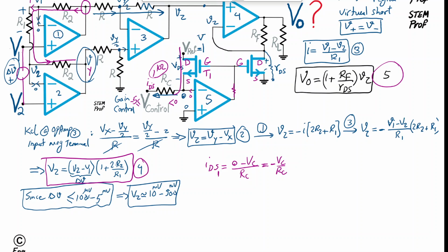Practically, it's usually recommended to have a resistor with a small value, but as I said, there are practical considerations that are not mentioned here because they are not core to defining the operation of the circuit, though they are needed practically. So let's just assume that the output voltage of the op-amp is directly connected to the gate.